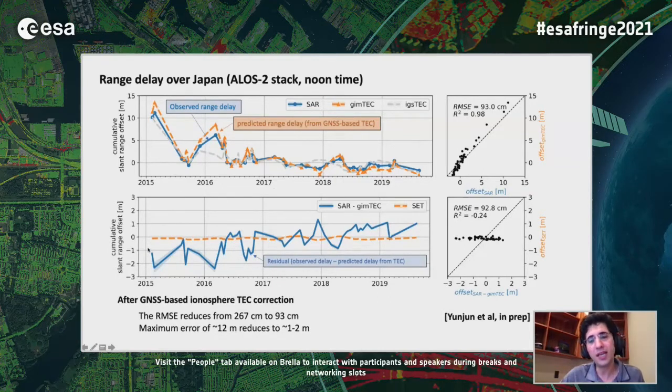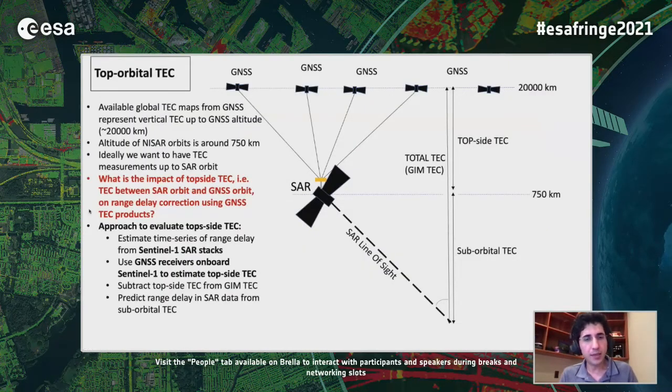And if we look at other sources for this L-band data set, we looked at solid earth tide, which usually, after the ionosphere, you would look at. And we see we are still too far from solid earth tide. And 1-2 meters, we thought it's still ionosphere. So what could it be? We got GNSS TEC data from GNSS colleagues that they usually take.